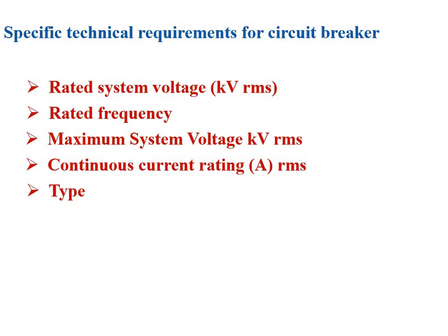All these, the continuous current rating, and the short circuit current rating also you have to consider. So different parameters are required to be considered to specify the type of the circuit breaker. That is also one important requirement of the circuit breaker.